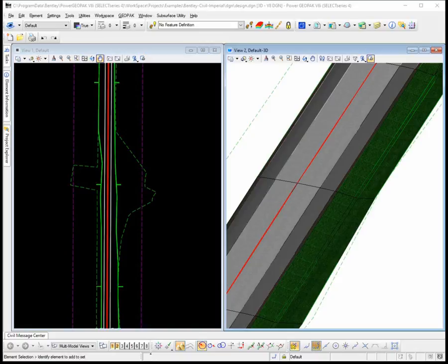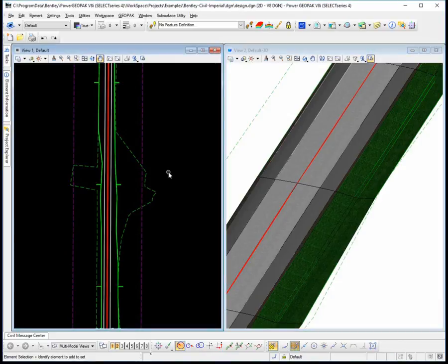During the design process of a corridor, one of the things that you have to do is to work on the roadways, the shoulders, curbs, sidewalks, etc. And then you'll have to work on your end conditions tying to ground. One way to expedite the processing speed of the corridor is to not have your existing ground surface active until you're actually going to be working on the end conditions. Because a lot of the processing requirements for the program are done within the end conditions.